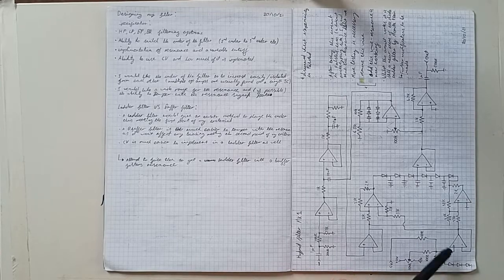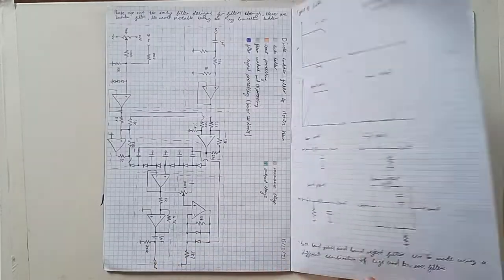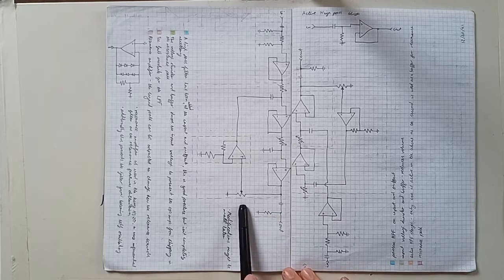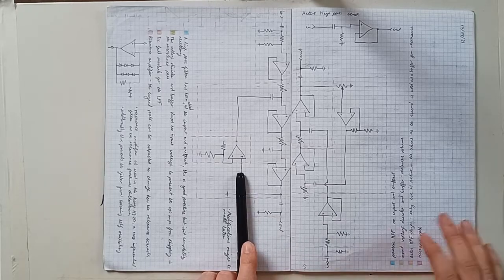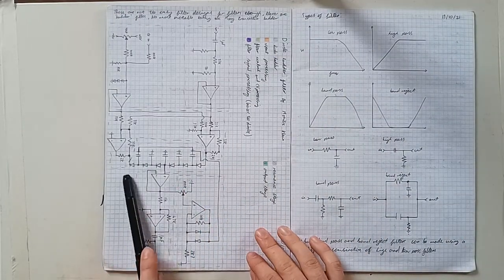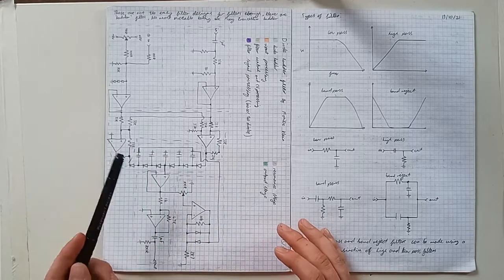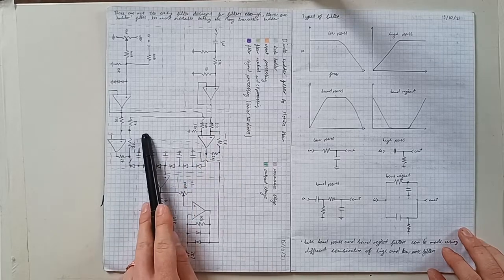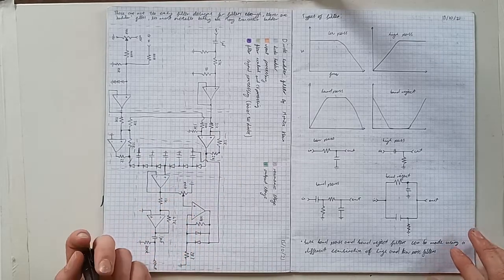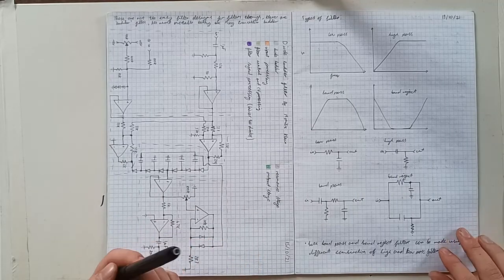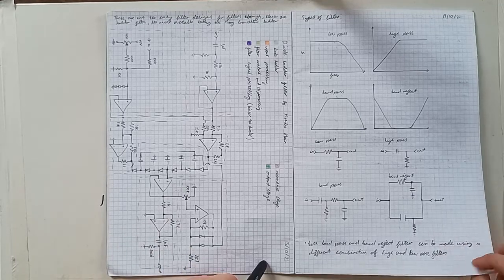And I'd like to note as well with my idea, as I talked about in my last video where I talked about the topology of filter, the resonance path of a cascade filter is more versatile, whereas generally the actual filter curve and control of a ladder filter is much nicer and more accessible. So I wanted the filtering of a ladder filter with then the resonance of a cascade filter.